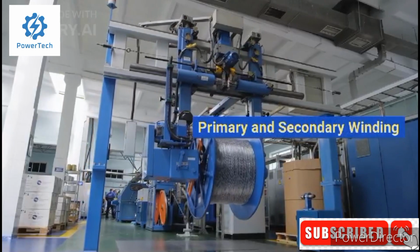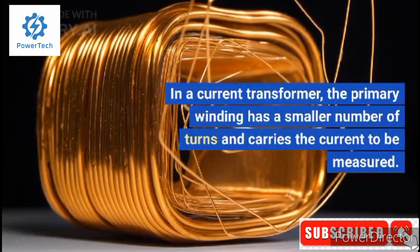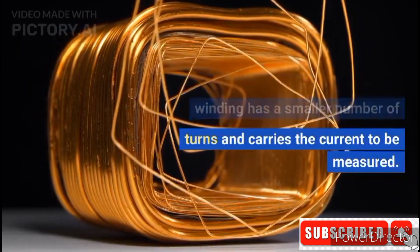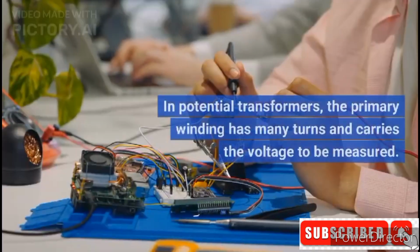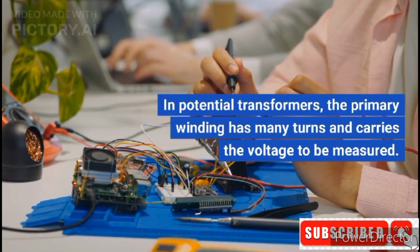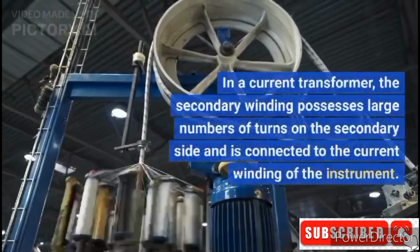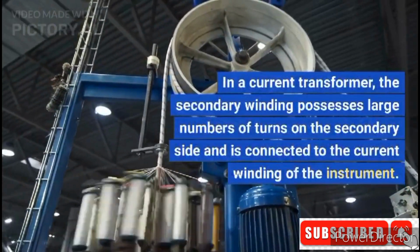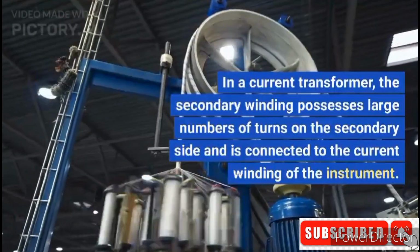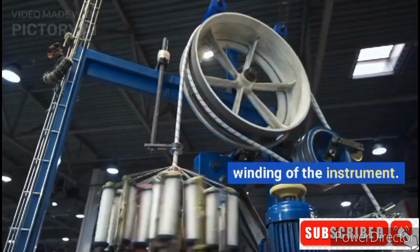Primary and secondary winding. In a current transformer, the primary winding has a smaller number of turns and carries the current to be measured. In potential transformers, the primary winding has many turns and carries the voltage to be measured. In a current transformer, the secondary winding possesses large numbers of turns on the secondary side and is connected to the current winding of the instrument.